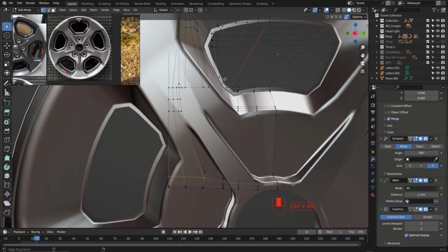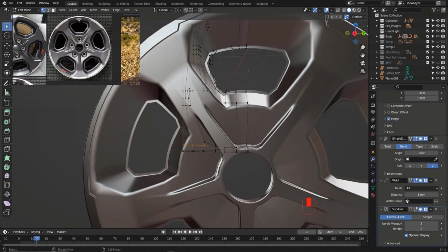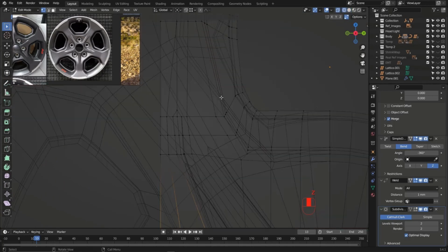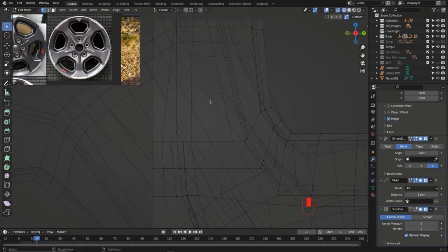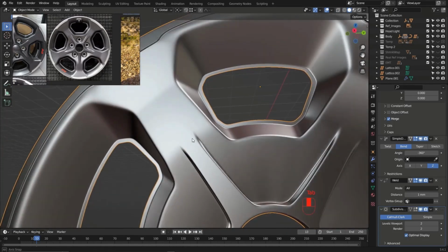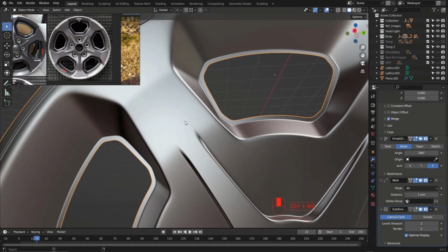You can go to the right view and do that there. Just go to the right view and let's use the knife tool to add an edge right here. So hit 3 to go to the right view, and then let's use the knife tool. You can hit Z to go to wireframe. Use the knife tool and let's create a cut that goes like that, and confirm it. As you can see now, when you tab, we don't have these lines here.